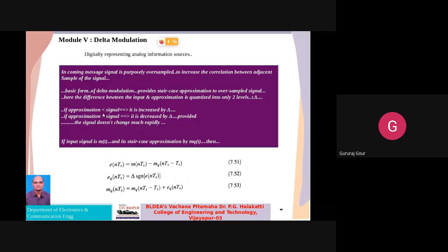And here it is represented by 0, because the approximation falls below the signal level. In all these cases the approximation is above the signal level, so it is represented by 1 1 1 1. So we use 1 wherever the approximation is more than the signal.